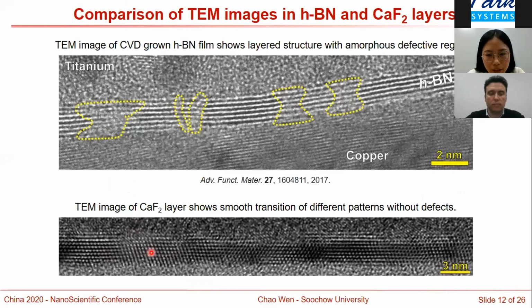into one another very smoothly because this is one special quality of the ionic crystals. And if we look here, we do not see defects. Actually, here I didn't put any slide, but if you look at the grain boundaries present in hafnium dioxide or other materials, you can see that the grain boundaries are different. Here the only thing I can say is that thanks to molecular beam epitaxy, it gives us an example. With larger regions, we do not see the grain boundaries. And the different orientations are related to the property of ionic crystals.